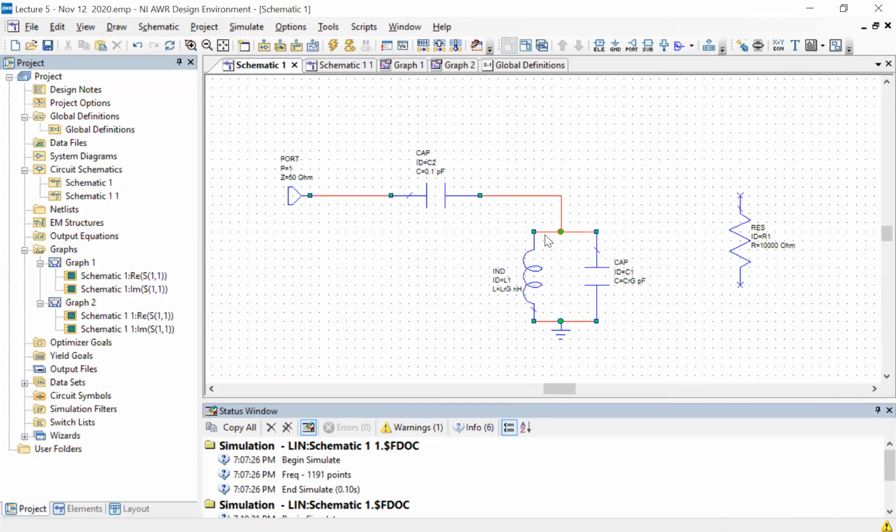And usually that is the situation, because you work with very small coupling capacitance since you typically want large Qs. And then here you might want some reasonable size capacitor, which is possible. But again, this entirely depends on the kind of circuit. Maybe you have a circuit which has a naturally very low capacitance and you cannot do anything. Then this has a much bigger effect. You can even double the capacitance, and then you have to be very careful about what will happen to the frequency. Right now, this is 10 picofarads and this is 0.1. So it has only increased by 1% in the capacitance, which means 0.5% in the frequency, because it goes as the square root of the capacitance.